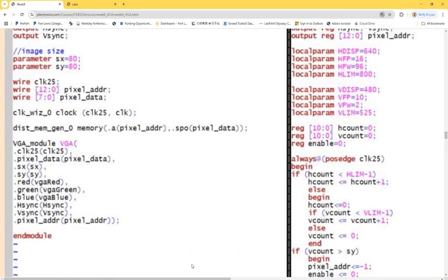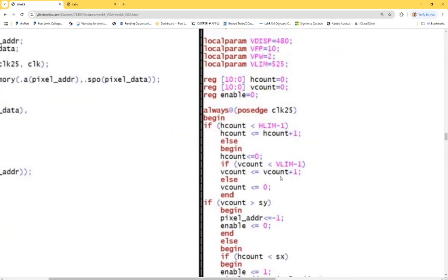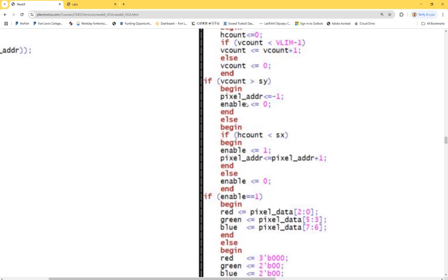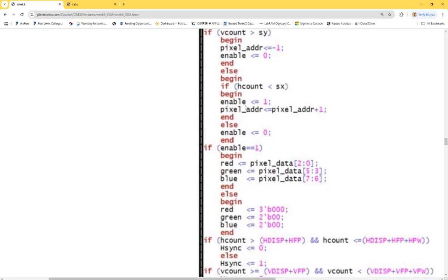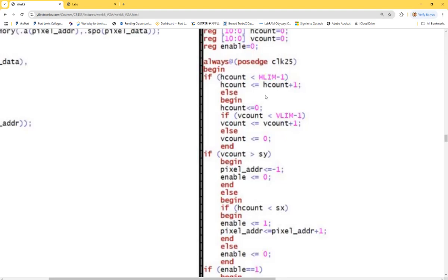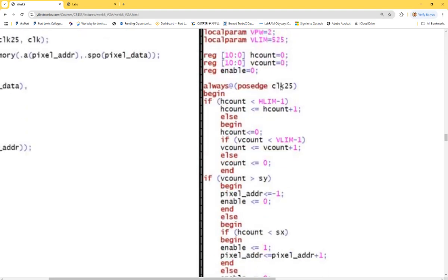See, all these ones are turning on the flag. All these previous if statements are just playing with the enable flag. And because this is not a C program, where instruction pointers take instructions one by one, this is just hardware. When you are programming hardware, everything will be implemented at the same time, and it's being synchronized by the clock.